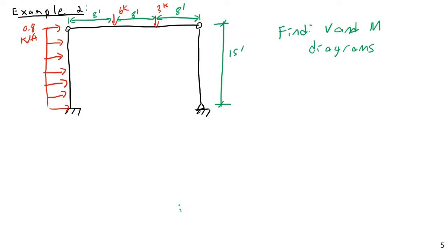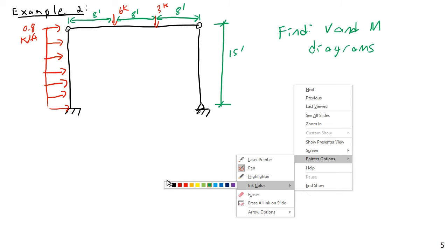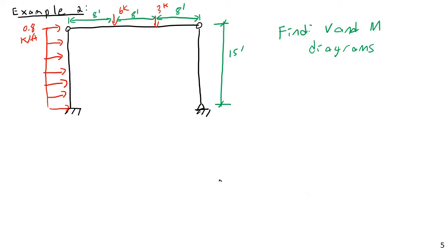All right, so the first step is going to be to break this into pieces. We're going to break this into pieces and do an exploded view, look at all the internal forces, then solve for the internal forces. Again, we're going to be able to do this primarily because this is a statically determinate system. In another video, we'll put together something illustrating the method of calculating whether a frame like this is statically determinate